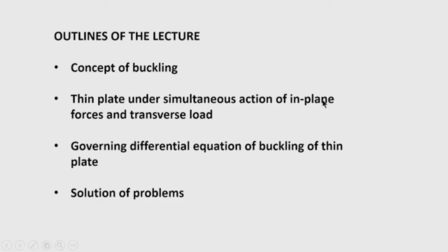In the derivation I will take the in-plane forces as tensile, which is considered positive, but in case of buckling the tensile force has to be reversed, that is, it will be compression. So, just by reversing the algebraic sign of the in-plane forces, we can get the equation of buckling of the thin plate.